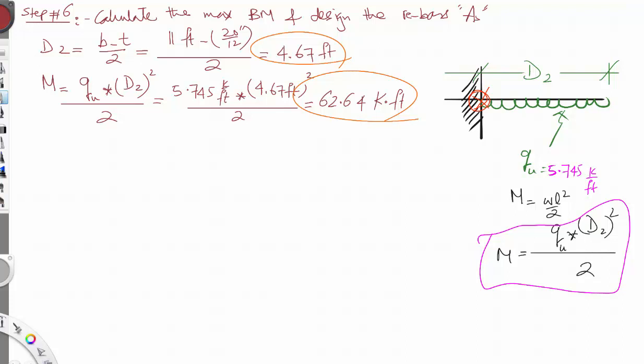So now we go back to the reinforced concrete design in this case. So now we need to calculate, like I said, we have the following equations to use. Mu equal to Ru b d squared, and then steel ratio equal to area of steel divided by b and d.